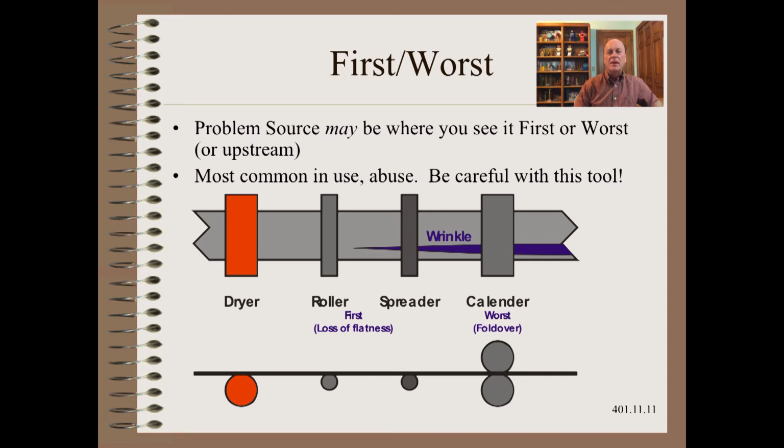An example is a truly severe wrinkling source can move upstream of where the problem roller actually is. Another example is that the source may be even further upstream yet, such as a currently invisible defect in the incoming web that may be coming from a different machine, or even a different company, or even a different country.